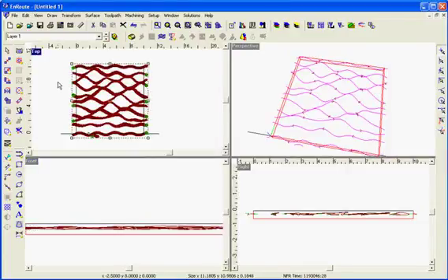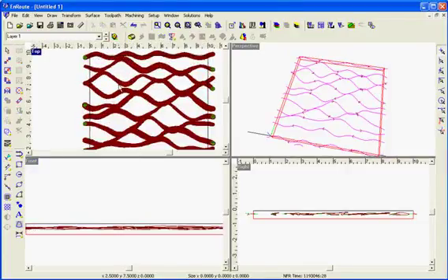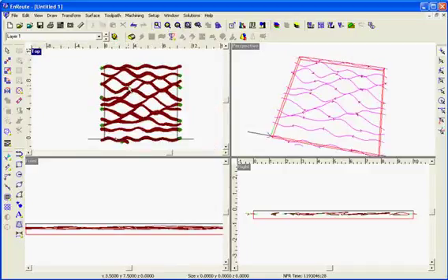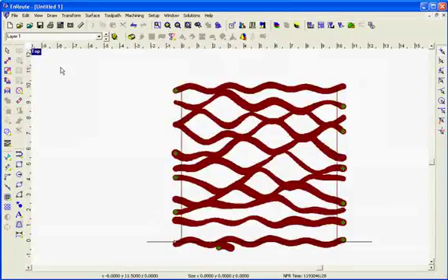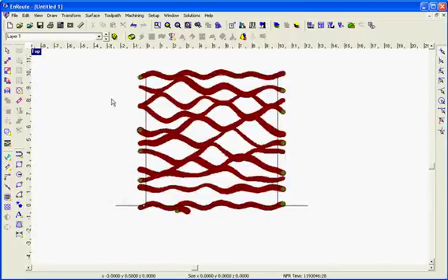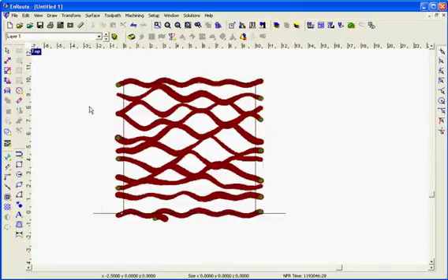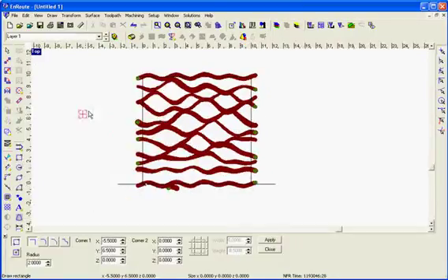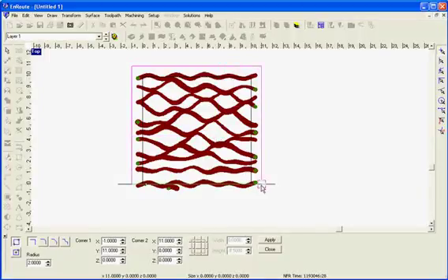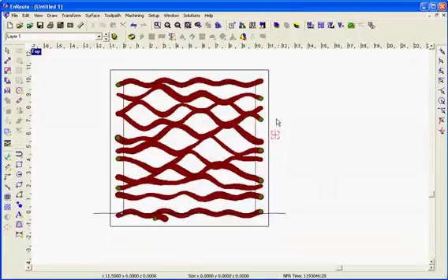If we hit F9, it will show us the width of each of the cuts in the material. Now let's see if these parts fit up correctly, and an easy way to do that is to do a 3D simulation and save your simulated part as a relief and see if they match on all sides. Because the only toolpaths that simulate are the ones within the material being simulated, I'm going to use my rectangle tool and draw a little bit bigger shape around my plate.